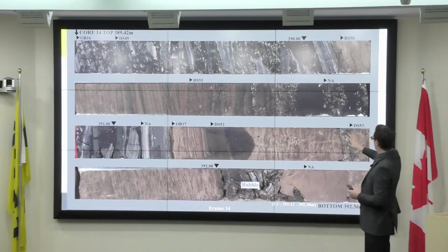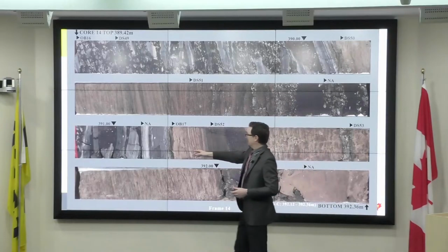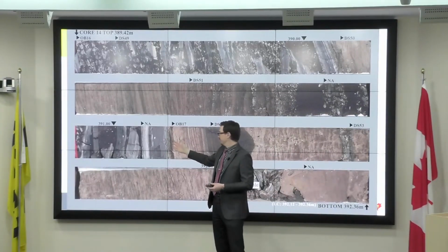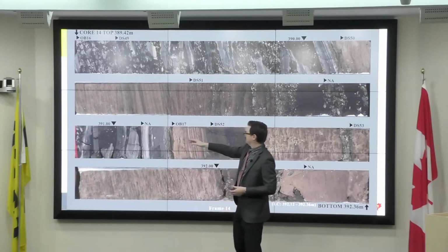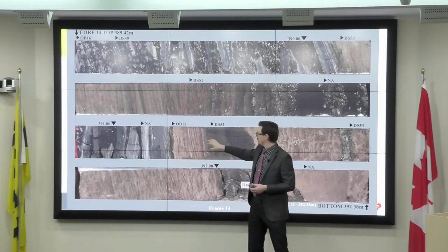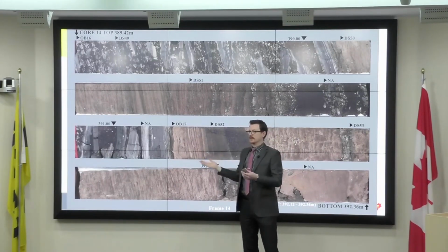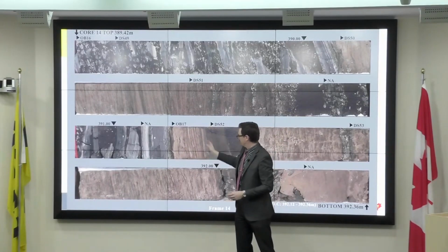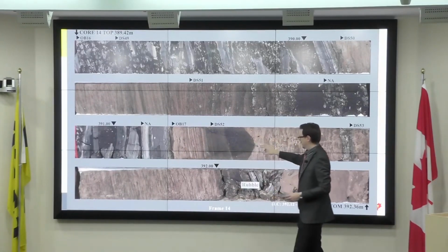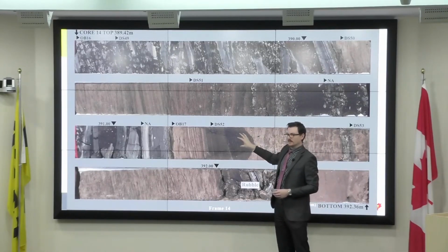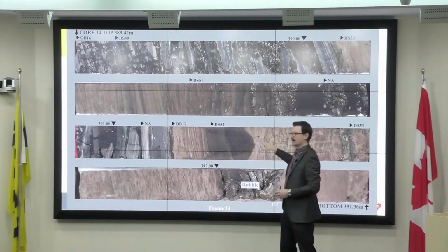As we continue down, we get again into some more clast zones, and then we come into a thicker clast here. This may be actually more plate-like, maybe almost in situ, and is quite extensive, possibly. And it has potentially trapped, again, some of this better, more steam-swept sand underneath. So the steam has become trapped up against the underside of this mud bed and then really swept out all the bitumen from here. We have a little anomalous zone here, this lens of bitumen that's sort of residual. Not clear why that's there because there's no mud associated with it to trap it in place.